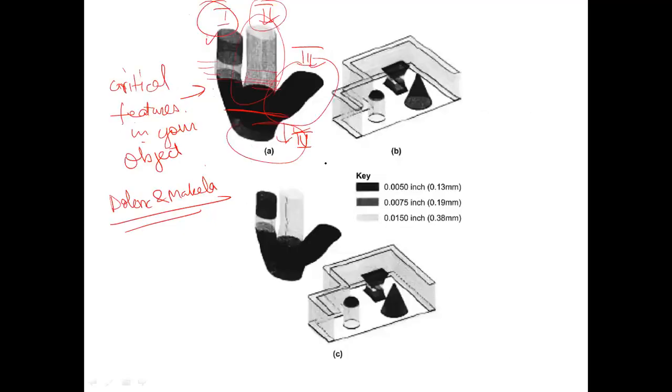And what you did was, each layer now was defined on the basis of how many slabs are actually needed to create the part. Like for this part, you had finer layer thicknesses, whereas for this part, you can have thicker layer thickness. So depending upon the cross section of that individual part, a single object can have local adaptive slicing as compared to uniform adaptive slicing. So every feature, every portion, every significant region of your model can be sliced separately.